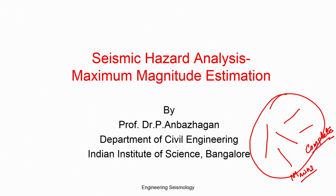The process of estimating the maximum probable earthquake or maximum credible earthquake at any seismic study area is actually the process of estimating the maximum magnitude. Today's class we are going to talk about maximum magnitude estimation methods, and how the seismic study area is related to your Mmax estimation.